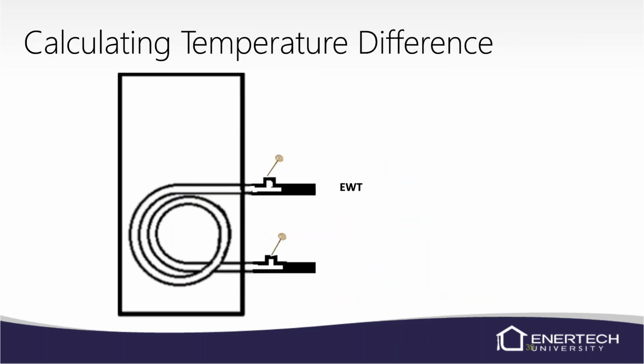Temperature difference, it's just doing math. I'm sure you guys have done temperature difference on air quite a bit. Basically, water in, water out. So in this example, we have 36.8 degree entering water temperature and 31.2. If the water temperature is higher coming in than it is leaving, we know we're in heating mode because we're extracting heat from that 36-degree water and putting it into the refrigerant circuit. So we lowered the water temperature by roughly 5.5 degrees, and that 5.5 degrees went into the refrigerant circuit.